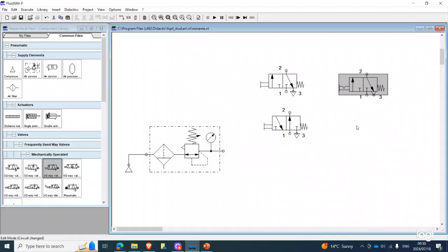So now I discussed that a normally closed push button doesn't allow the supply of air, right? Up until a point where you press it, that's when air flows through, because it is in an initial position, it's closed, right? And then a normally open is always allowing air to flow through up until a point where you press it, that's when it cuts the supply of air going into the circuit, right?